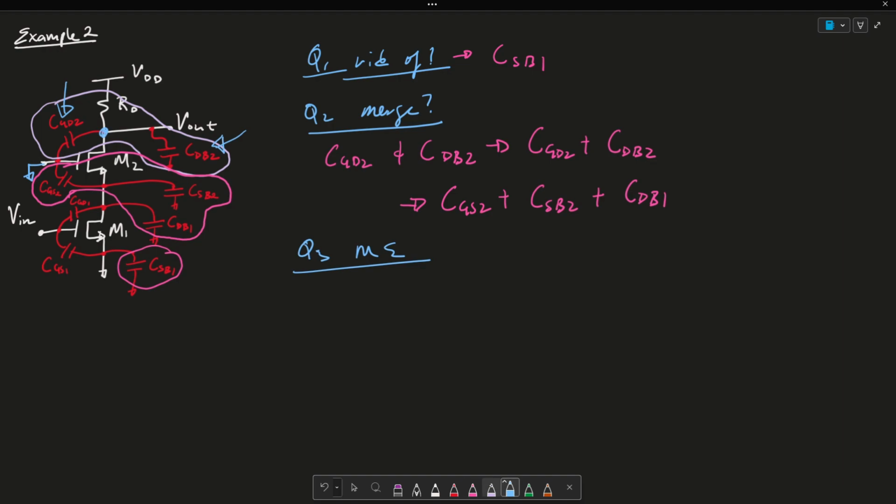Okay, so the last question is going to be, which capacitor experiences Miller's effect? And again, as we can see, only CGD1 right here is affected by it because it's connected to both Vin and this output voltage here. Let me call this V1, okay, on either end. So then the answer to this is CGD1.